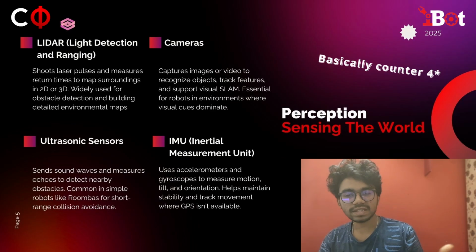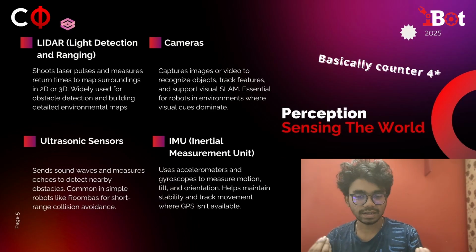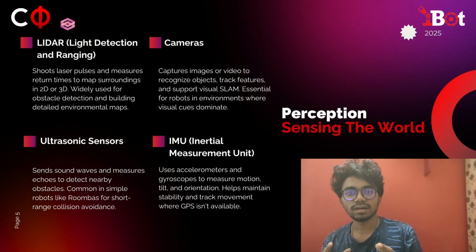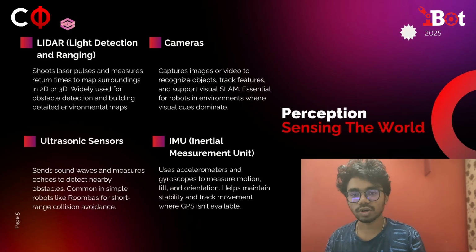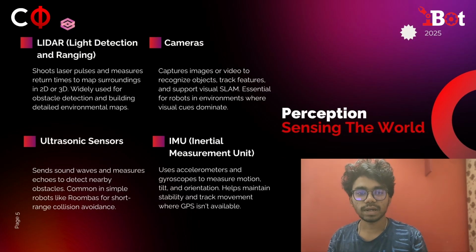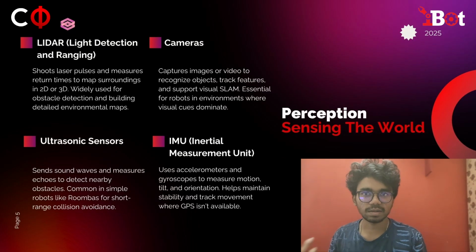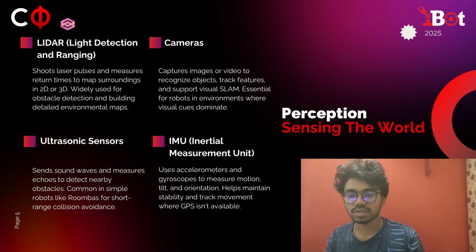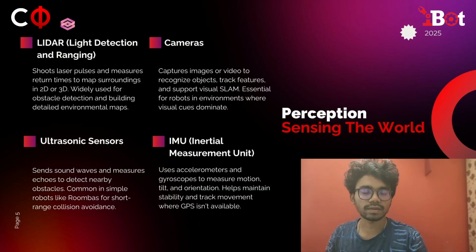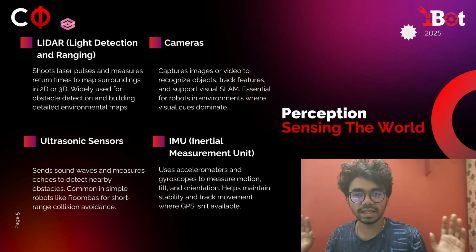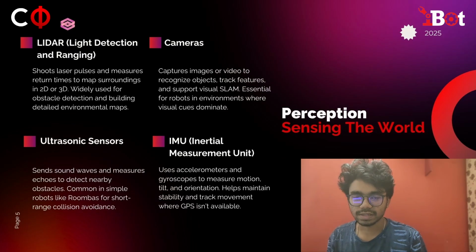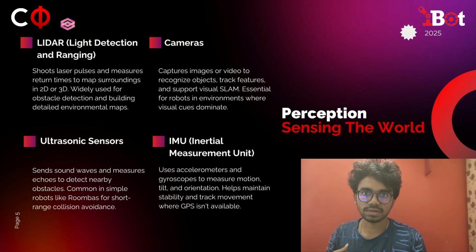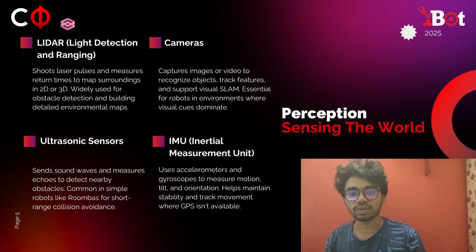Sound propagates slower, so it has higher clarity at lower distances. But at higher distances it is not as effective because sound gets distorted a lot by the surroundings. Light does not get as distorted as sound. So it's much better to use a lidar sensor if we are aiming at a larger area and we have a lot more budget than for ultrasonic sensors. That is the basic difference between lidars and ultrasonic sensors. I got confused about this when I was doing my internship, so I just wanted to put it out there and clarify.